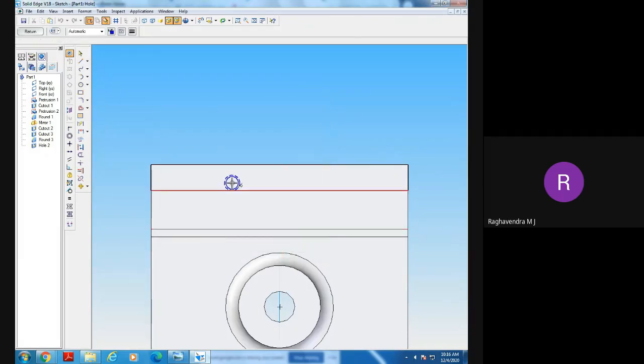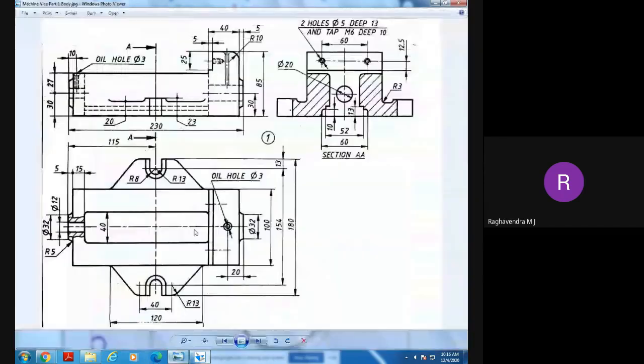Now, where I need to place this? That is very important here. Okay, don't place it on the red mark here, or tangentially anywhere. See, there is a relationship. Tangential relationship is coming. We cannot modify later. Just move down. Still move down. See here, no disturbance, no relationship will appear here. Just place it. So now go for the positions.